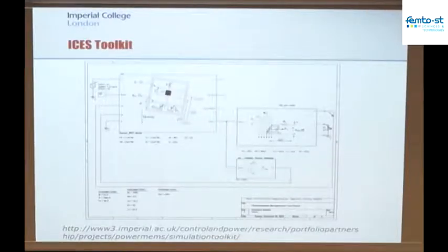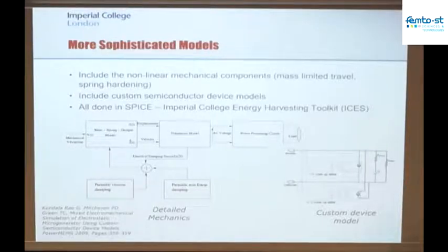Yeah, so this particular toolkit that we've produced here has got models in for the various different damping mechanisms. The difficulty, particularly simulating Coulomb damping, is that you get a sort of stiction where the thing will move to a certain point, and then in the simulation environment you get lots of zero crossings, which will slow the simulation down quite a lot.